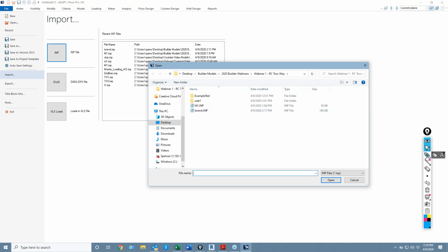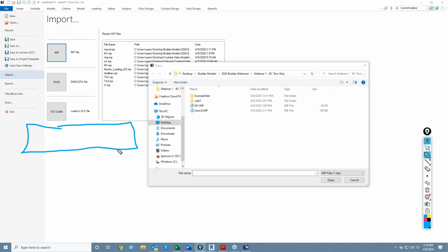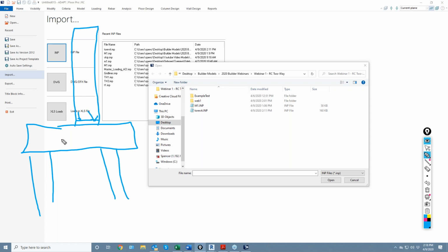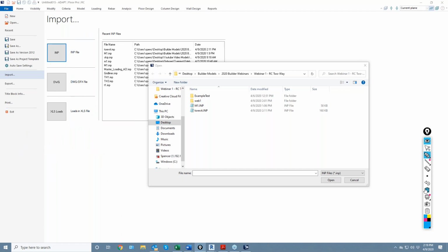An example of this would be if you have a transfer slab, this might be post-tensioned, and then you have an RC structure above that's analyzed in ETABS. Maybe I need to get these reactions at this level down to this mat or this transfer that might be post-tensioned. And so we can import this set of reactions and apply it into ADAPT from ETABS, and then carry on with the PT design for this transfer within ADAPT. So that's the intended purpose for the integration console.